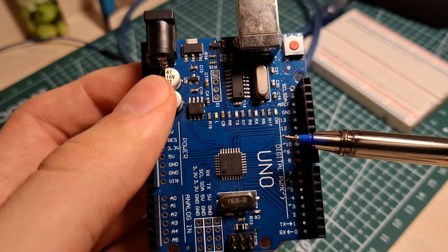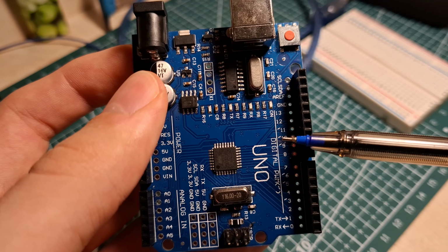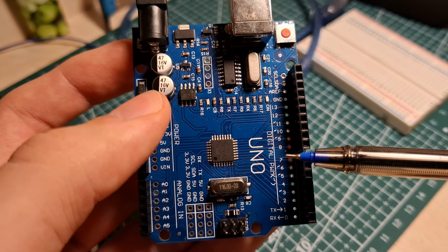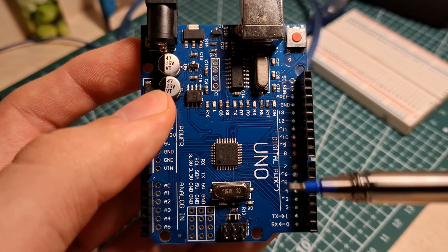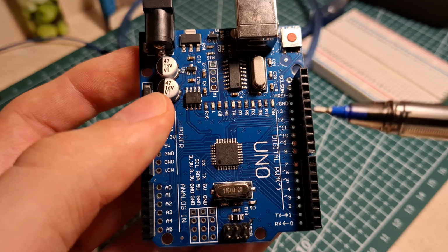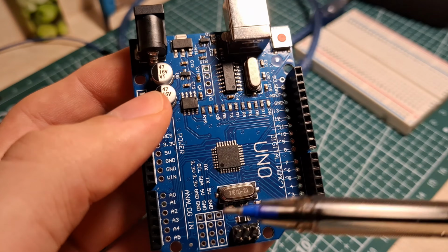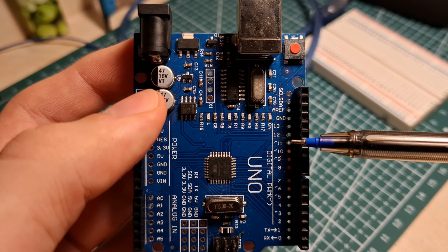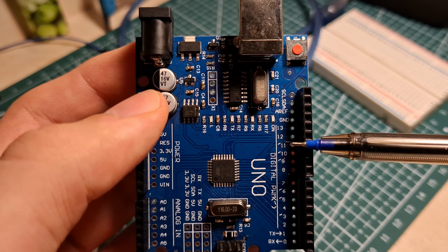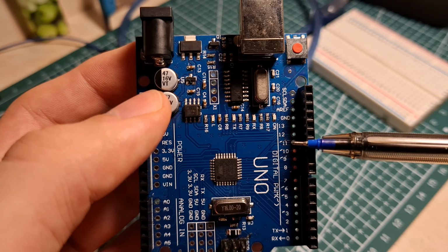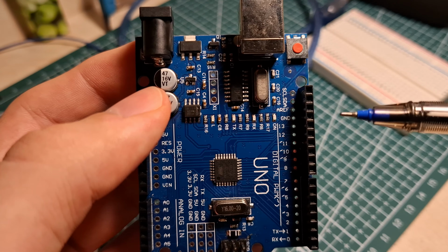And there are some pins which have a symbol in front of them. These are PWM pins. For example, the third pin, fifth pin, sixth, ninth, 10th, 11th, all of these pins are PWM pins. What is the meaning of a PWM pin? It can be used as a digital pin and also as an analog pin. So you can use them by your need. If you say to Arduino, for example, analog read 11th pin, it means that you are using this pin as an analog pin and at the range from 0 to 1023.